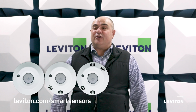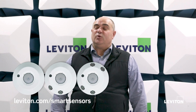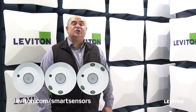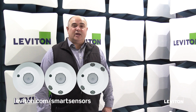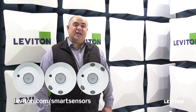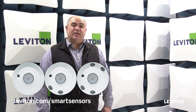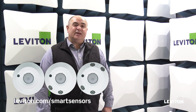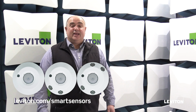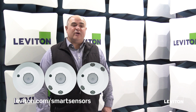Again, this ladderless commissioning doesn't include just adjusting the sensitivity. It will allow you to adjust the scheduling. It'll allow you to redo the grouping or networking, as well as saving additional templates. Again, understanding that the template does reside within the device and can also reside within the phone or tablet that was used to program it, and can then also be emailed as a file to whoever else wants to use it.